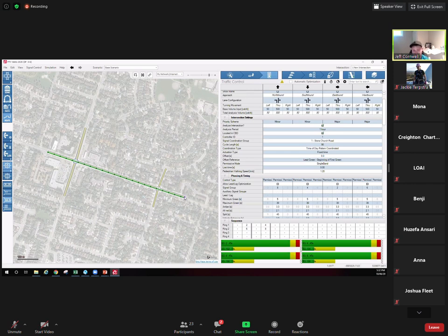So I'm going to give everybody a minute to do that. If you're having any troubles with that, it could be because you didn't connect the 2 intersections properly, which is why I was trying to make a note of that at the very beginning. Because when I first did this, I did the same thing myself, and I couldn't create my network properly. So you click on the route button, which again is over here, and you draw a purple line from one end to the other. And once you click, it turns green. So again, I have this purple line here. To get rid of the purple line, you just double click. And then it creates these 2 pins.